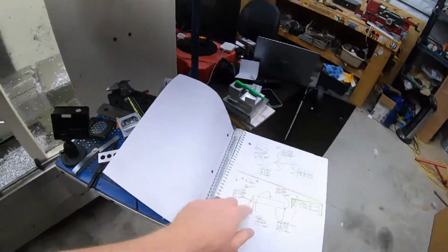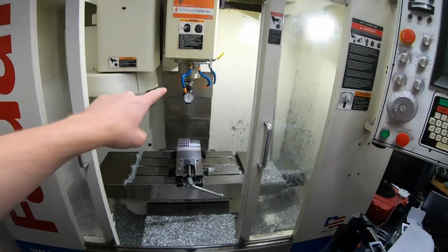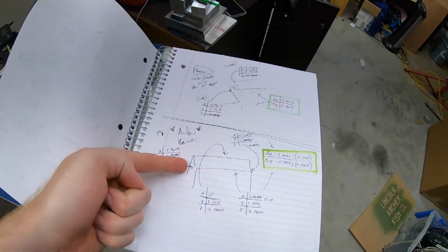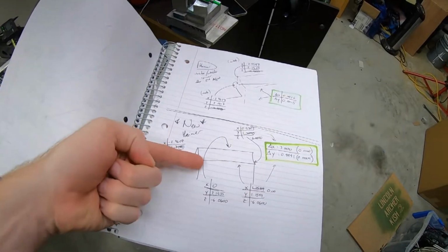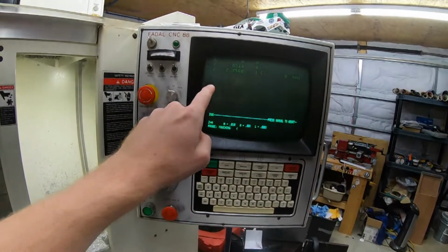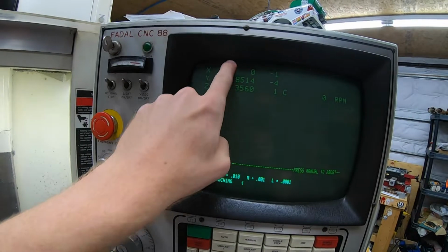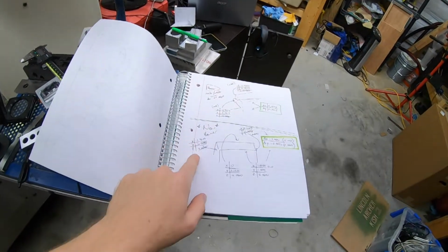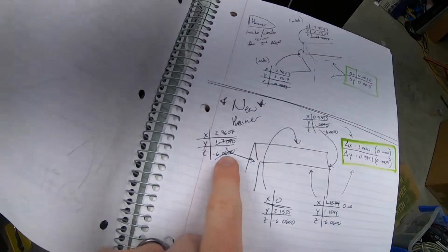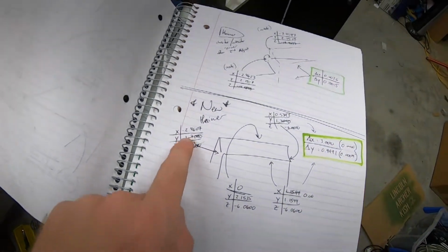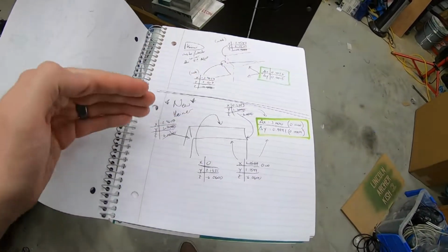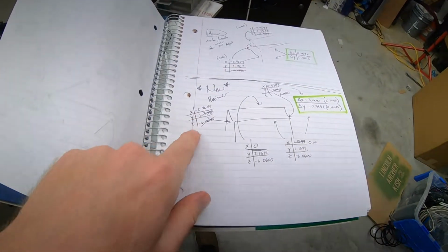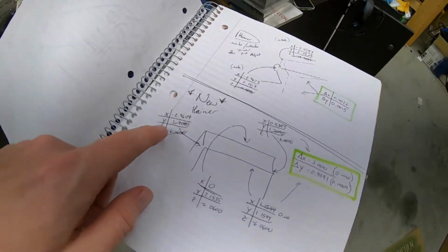Alrighty guys, I just did the math, and I'm smiling real big right now. So at each point on the 1, 2, 3 block, I went to a position, and then I wrote down what my position was, X, Y, and Z. And I document all 3 of them. That way I can tell if I stayed at the right Z height and the Y position on this side and then on this side. So I did that, and here are my numbers.